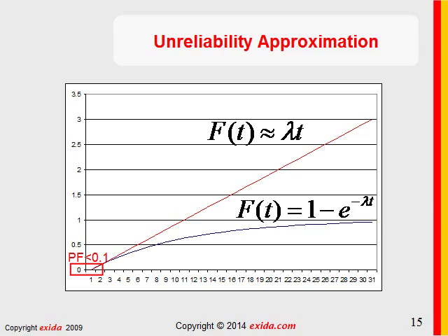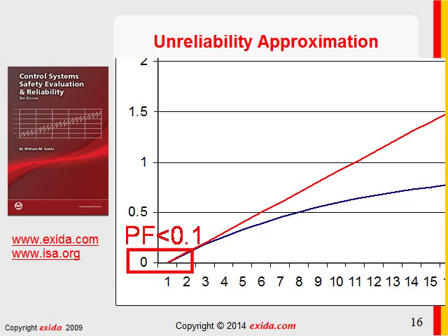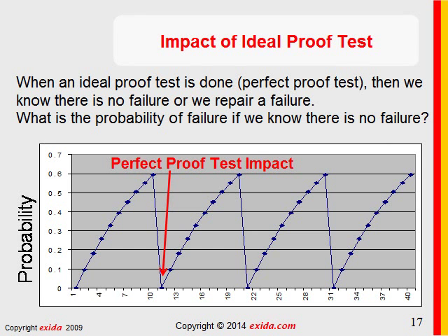Most of the time I've calculated a number like 3 or 4%, and that is just fine for safety, because even SIL 1, the worst number on the entire chart, was 0.1. So we are going to be working entirely in this range, boxed by the red box, and so we're going to be using the approximations to make things simpler, and that's exactly what the various committees have chosen to do. The problem is, of course, they didn't recognize all the variables involved.